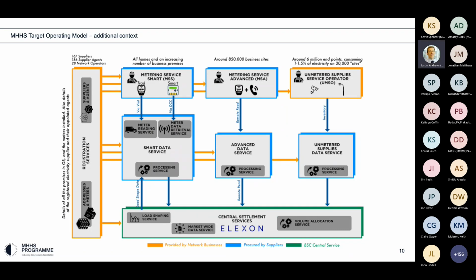And is it worth just saying what measurement class indicates, Kevin? Currently, the existing measurement classes divide meters up if they're domestic or non-domestic, if they're whole current or CT, and currently by the size of customer as well. So are they over 100 kilowatts or less than 100 kilowatts? Those distinctions will all disappear.